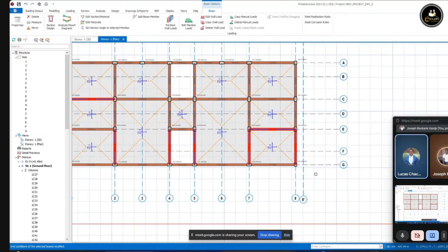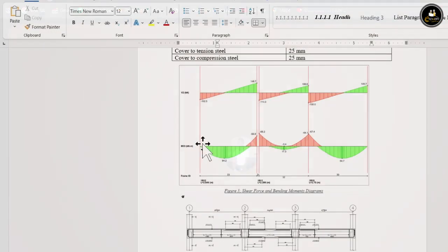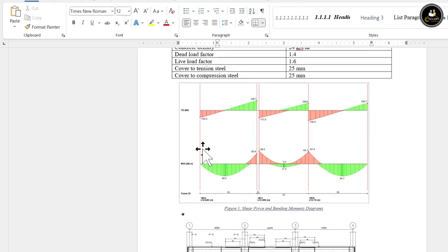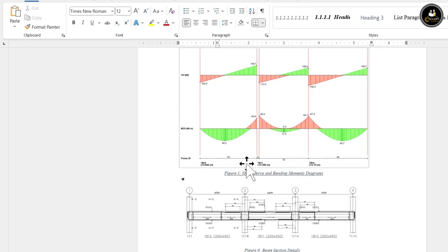You also do the manual calculation. The moments at those points are zero. So we are only looking at the places where we have zero moments. I don't know if I have the entire plan view of this. But if we keenly observe your diagram, you can easily tell places that will be having zero moments and those that will be having the extra moments.